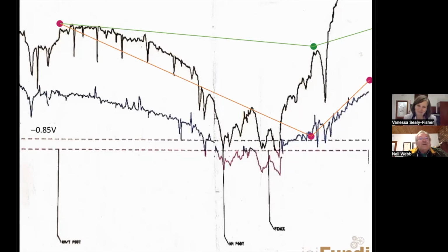They were quite astounded. The point about that was that the ground conditions in that area were pretty bad, and the cathodic protection had not functioned. So in this slide, you can also then see that had we done the full pre-assessment, we would have picked up from a close interval survey that there was a significant area of poor protection from a corrosion protection point of view, and probably would have done something about it. This was actually done before the implementation of close interval survey. And this project was one of the first really big implementations of close interval surveying in the early 80s.